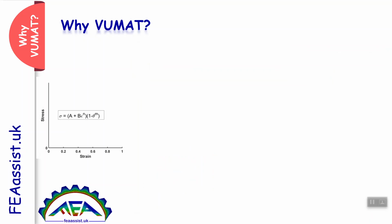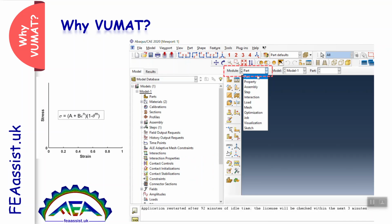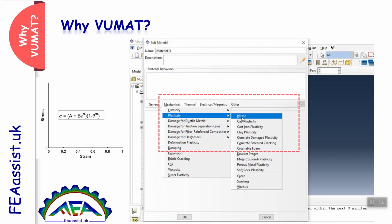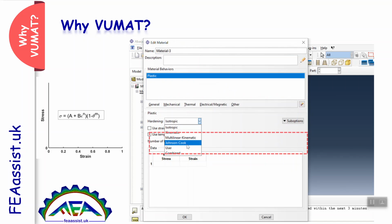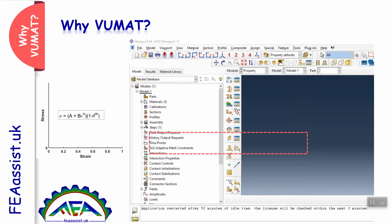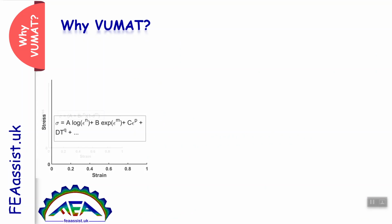If you have an equation and the equation is included in Abaqus, then you can go to Abaqus again, to property, materials, mechanical, and instead of entering the points, define the behavior. For example, here it is a Johnson Cook. You can enter the parameters and constants of your equations. Abaqus will solve your problem in all points based on this equation. This is more precise because you have an equation.